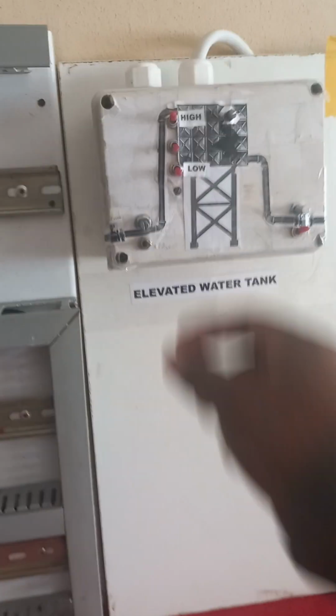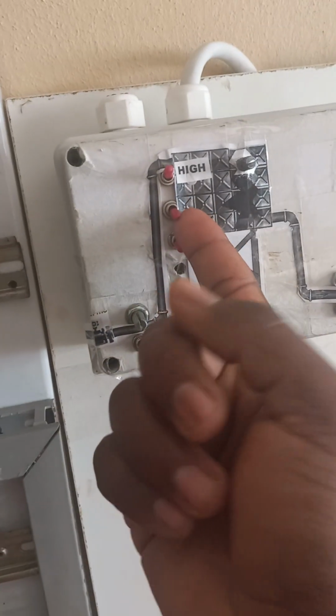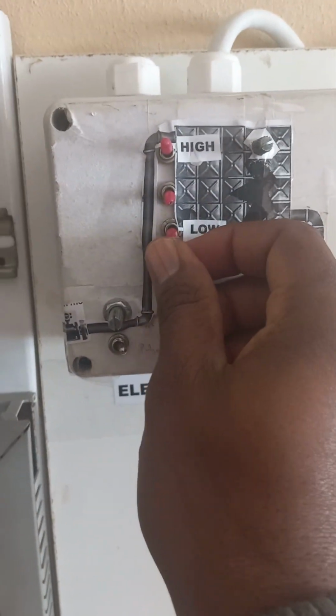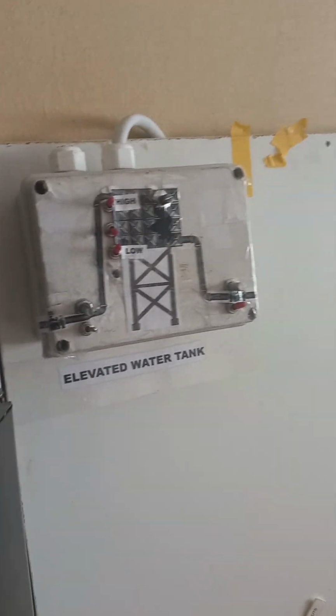First of all, let me check the response of the EWT, the box and the SCADA, to show you that they are corresponding and doing well. This is the low switch, it's activated, it's down. There you go, it's flashing. I can put both of them active. Let me read the high level. You can see both of them flashing. In the normal case, the level transmitter and the switches go hand in hand. So let's try to simulate and see what is going to happen.